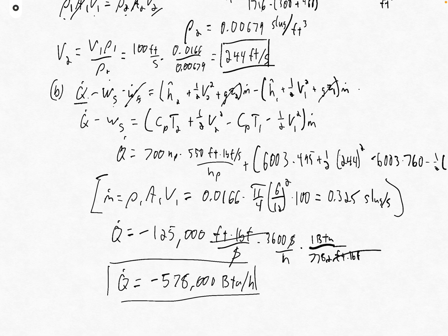And so in this case, our heat transfer being negative indicates that this is a loss from the control volume. Think about something like a heat transfer loss through the sidewalls of this really hot vessel that's sapping some energy from a control volume, the type of thing that you might want to fix with insulation on the outside. But regardless, the fact that we're getting a negative number here means that we have a loss.